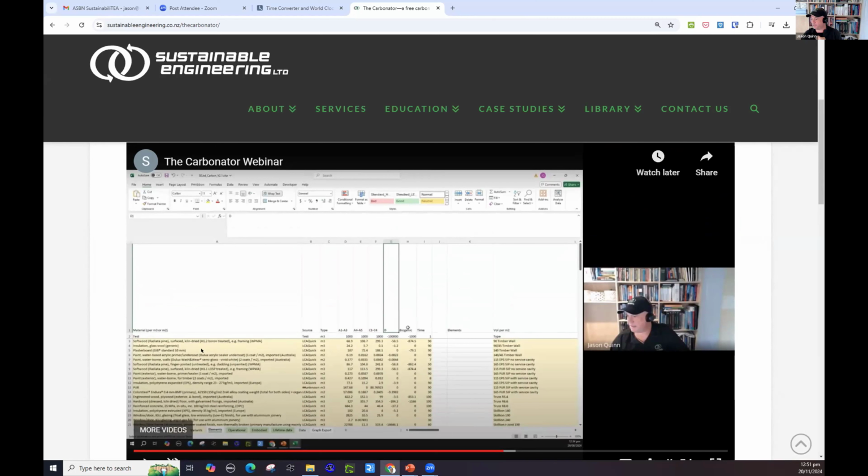What you need to do is put those layers in as materials. We've already got materials that we use a lot in there, and they're reasonably good for Australia once you fix the grid factor, right? Which is just on the data sheet, by the way. It's this one called data right here. There's just a grid factor. It's a single number. You can just type 0.7 and then you're sweet.